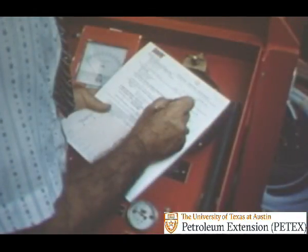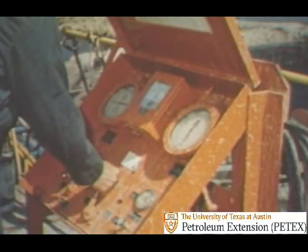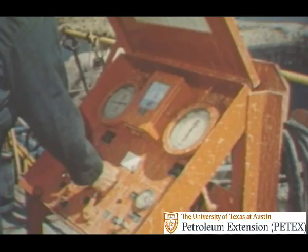Over at the pressure control panel, a worksheet is filled out with pertinent data necessary to kill the kick. Calculations show that the mud weight needs to be increased 0.2 of a pound to control the kick. The driller opens the choke control on the panel. The kick will be circulated out of the hole through the choke, and then the mud will be weighted up.